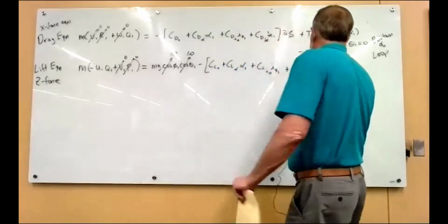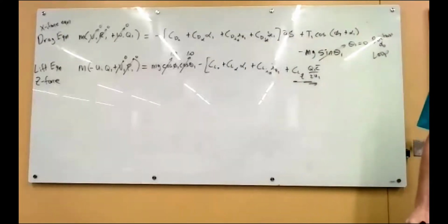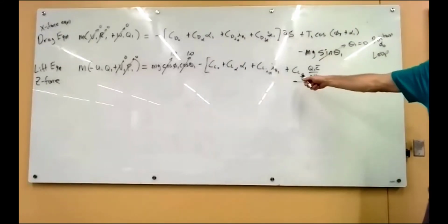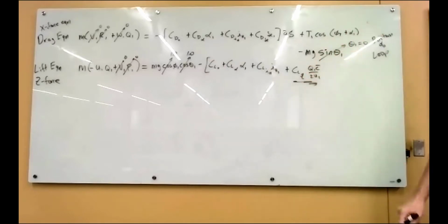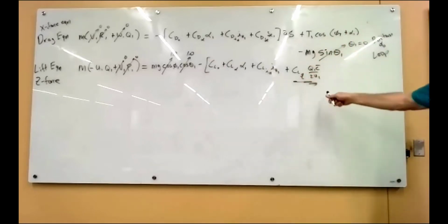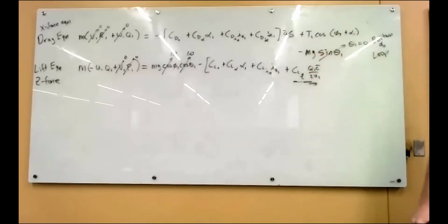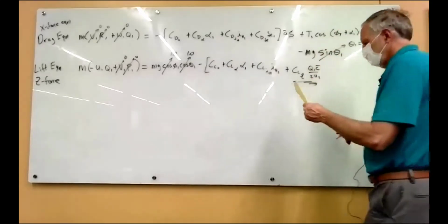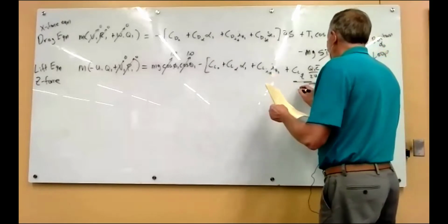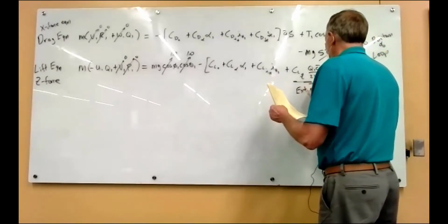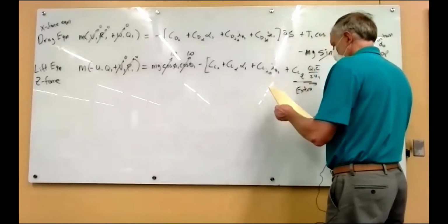And then here is the pitch rate term. I guess we didn't use this in the turn because the turn had P and R, right? No, my bad, we had that in there because P is 0 in the turn, Q and R were non-zero. So this is an extra term because of the maneuver.